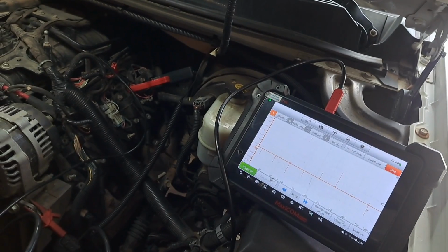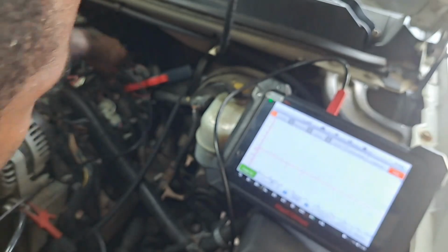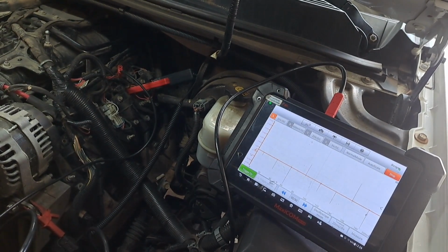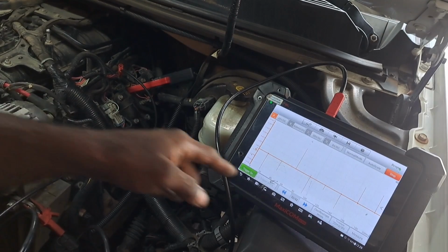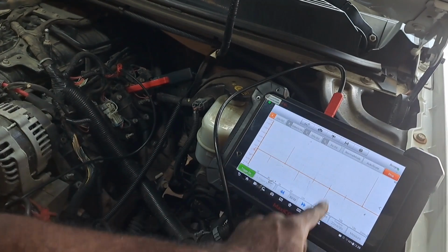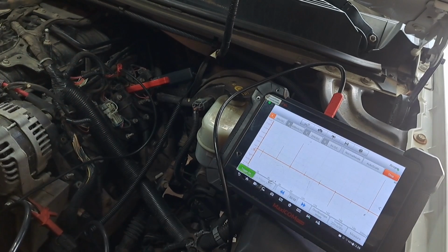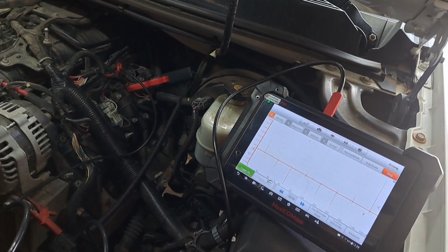Yeah, it's not doing anything. All the other ones would generate that square wave. Number 5 isn't doing it, and like I said, I'm not sure if it's an IGF, like a confirmation, but it does go in sync when it did work with the fuel injector, and I'm not sure if that had anything to do with it, but it may be worth looking into.